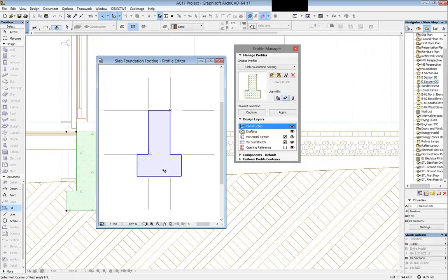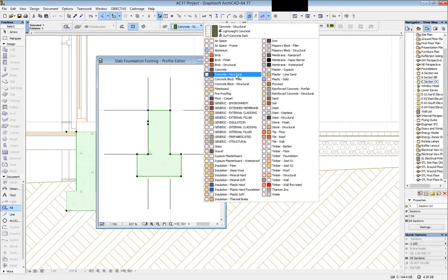So if I select this profile, you'll see it's drawn with a fill, and the fill is the building material. So when I actually go and draw that foundation, it is solid concrete, and I could get the volume required, etc. It means you can create any sort of complex profile using any building material you want to be used in wall, roof, beam, and slab. Very, very useful.